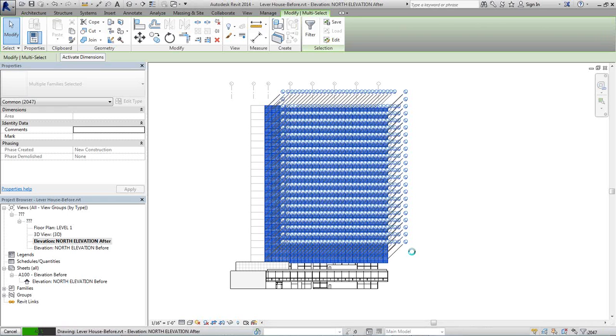I'll show you where the tool is, and then I'll tell you not to waste your time with it. Because drawing a couple of lines over this gets you exactly what you want in really short order, whereas fooling around with this profile tool that they have, it's just not really well developed, and just doesn't work very well.